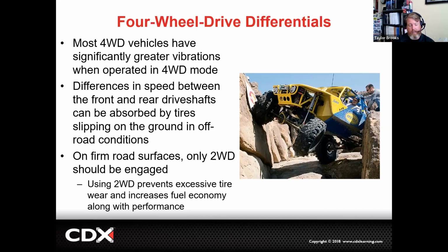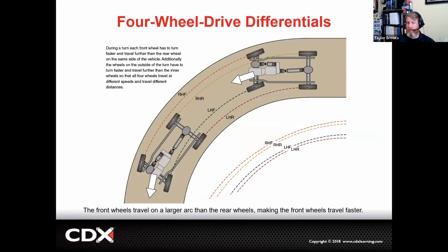And I was like, well, here's the deal. You're only supposed to drive in four low in what I have photoed here: serious off-road, speeds below 2 miles per hour, and in situations where you're trying to avoid getting stuck. He didn't want to hear that. We had to get Chrysler involved, and Chrysler unfortunately ended up voiding his warranty when they found out that he openly admitted, yeah, I'm in four low all the time. I want to have the traction. Now, it actually is making the vehicle more unsafe in that situation.